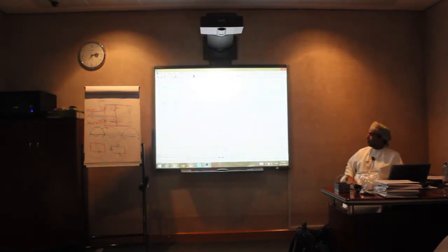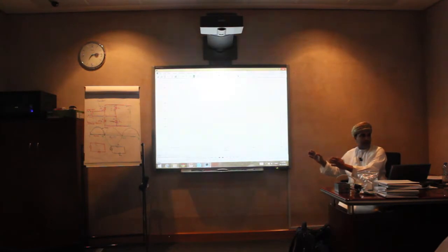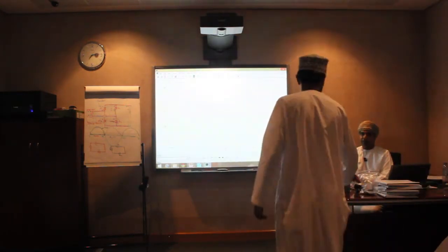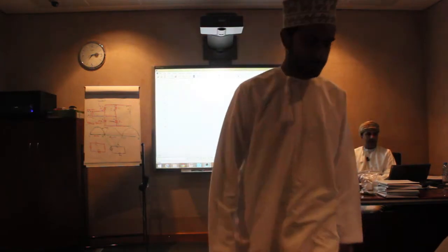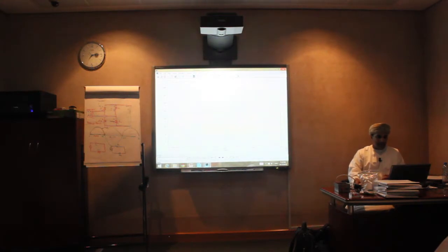So look at the output. It just rectified. Now, instead of AC, I'm having DC. The only difference is that I have some ripples on this one. Later on we can reduce those ripples by adding a capacitor, like what we said. So this is the output. If you would like to compare between this and the previous one, which was the half-wave rectifier, now the value of the voltage is higher for this one. Is it okay, Shabab? Is it clear?